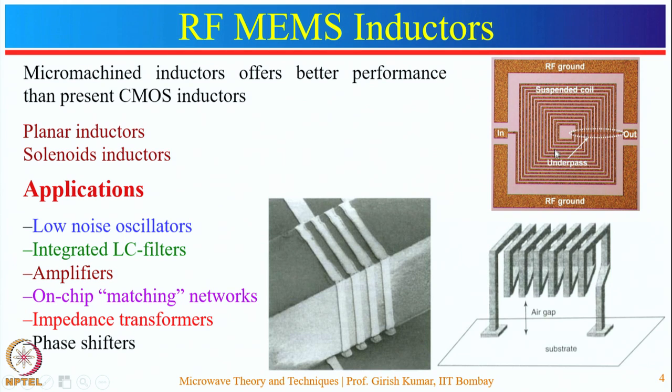Now, in case of spiral inductors, the size is relatively more. Additionally, they suffer from the direction of the flow of flux, and in case of meander type of structures, they provide the low inductance value. These problems can be overcome with the help of solenoidal inductors, but they are difficult to fabricate due to their 3D geometry. Here they can be made using the metallic strips over the core, but as I mentioned, the fabrication of these inductors is relatively difficult due to the limitation in the fabrication technique.